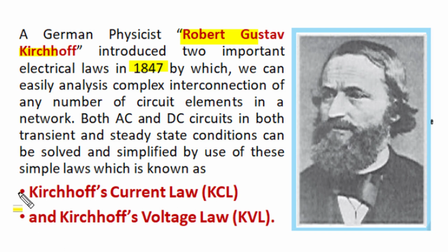Now these two laws, one is Kirchhoff current law KCL and the other one is Kirchhoff voltage law KVL, are based on two conservation laws. Kirchhoff current law is based on the law of conservation of charge and Kirchhoff voltage law KVL is based on conservation of energy. So both KCL and KVL are fundamental and universal in application. KCL and KVL can be used for both AC and DC supply circuits, and can be used both for steady state conditions or short time transient conditions. Let's study these two laws KCL and KVL first, and then we'll see some simple applications of KCL and KVL.